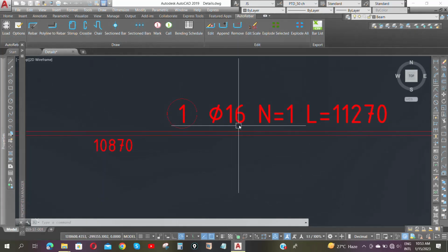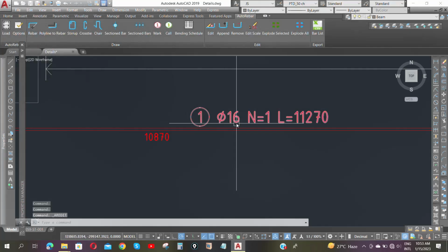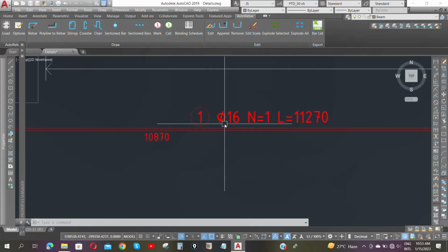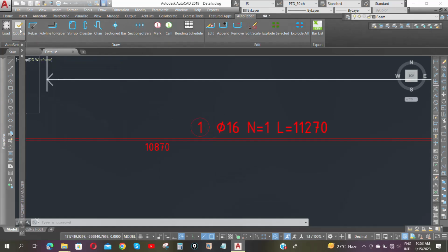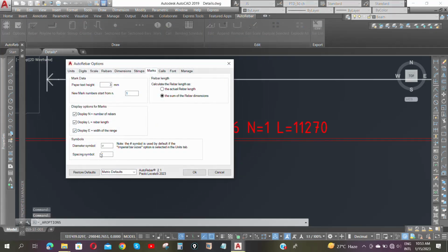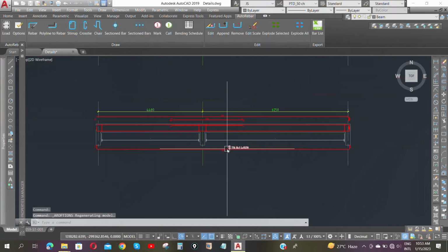So what we'll do, we change this bar diameter to diameter 16. So we indicate the type of reinforcement we actually want, so that somebody on site doesn't go and start using mild steel instead of high yield bar. Okay, so we'll go back to this section here and change this to T. So that is that.